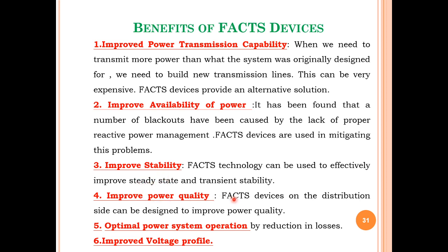Next, improve power quality. FACTS devices on the distribution side can be designed to improve power quality. There it can improve the voltage profile. Optimal power system operation: optimal in the sense I can use the system efficiently by reducing the losses. These are the points we have to remember for benefits of FACTS devices: power transfer capability, availability of power, stability issues, power quality, optimal usage of power system, and voltage profile improvement.